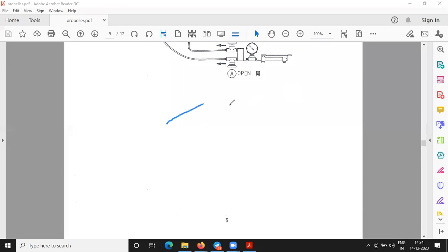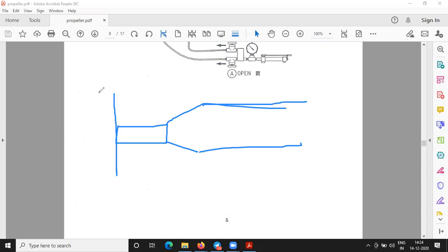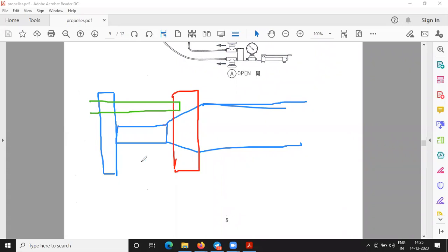Okay, sir. Again, in the dry method, what are we doing to remove it? Even though it was on the tapered portion, there is no oil provided to reduce the friction. You will have a strong back created at this point. A strong back is nothing but a strong plate. This is the propeller boss. You are connecting the studs to the propeller boss, and now start jacking with this nut.